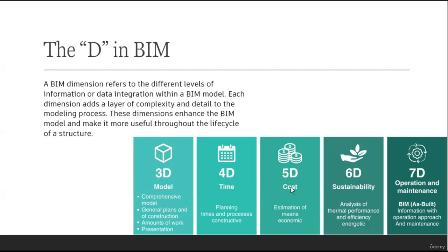Okay. Now the 5D involves the cost aspect of the project. Assigning cost to the 3D elements can help us obtain a 5D cost model. Using the 5D cost model, we can have a one-click access to the cost estimation of the project and can also have the supporting model-based quantities too. Any changes in the model are automatically reflected in the reports and schedules that are generated. So there is a saving of lot of manual work and any potential data entry errors.